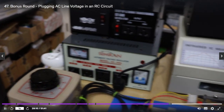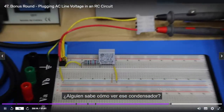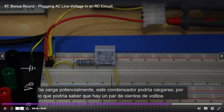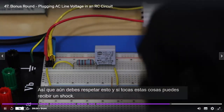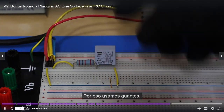Now, there is a way to get shocked. Does anyone know how? See that capacitor? It's potentially charged. This capacitor could be charged, so there could be a couple hundred volts sitting on this thing. So you still have to respect this thing, and if you touch these things, you could get shocked. That's why we wear our gloves. So you have to be very careful.